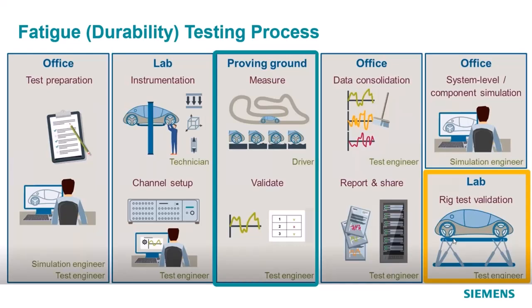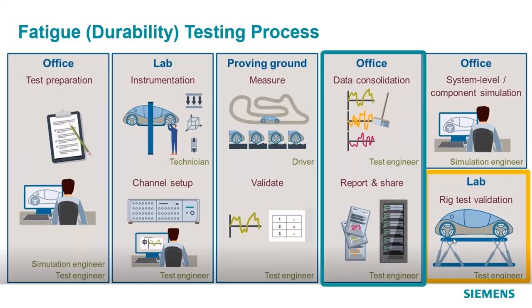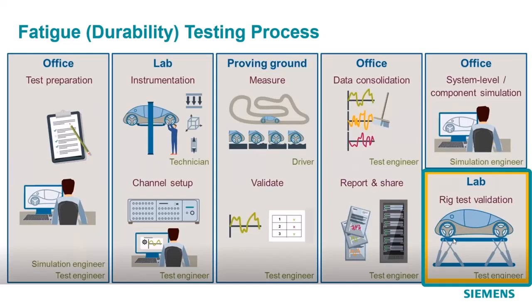You do the instrumentation, then put your product through its normal usage. In the case of automotive, there are proving grounds on which these cars are driven, and then you collect the data from those proving grounds. And these proving grounds can have different types of road surfaces, like smooth roads or concrete roads or Belgian blocks. All these types of different load conditions are tested in this. You collect the data from this proving ground, and then you analyze the data and come up with a load profile that you want to use for laboratory testing.